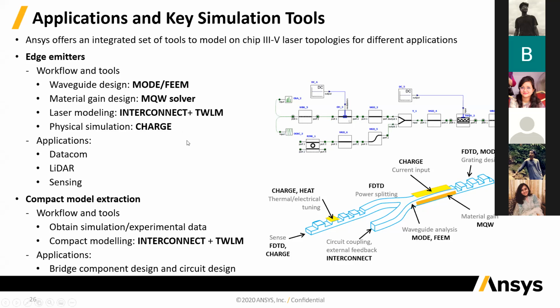So the waveguide part of your device, you can simulate with MODE or FEEM. Then for the active materials, you use the MQW solver, you simulate the stack and figure out the gain spectrum. Then you go to INTERCONNECT and use the traveling wave laser model to create a compact design for your laser. And then for the physical simulation of the stack, so that you can figure out when you apply a voltage, how much current is flowing through the stack, and how it is affecting the optical behavior of the stack, that's where you can use CHARGE.